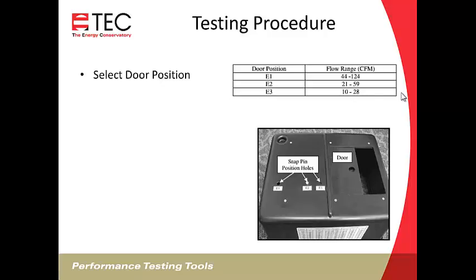If you've got a flow less than 20 CFM, then there's something seriously wrong. I mean, the minimum I've seen on ratings on fans is about 50 CFM. That's pretty typical. And if you're getting flows of less than 20, there's an issue with a stuck damper or a compressed hose, tubing, or the venting, whatever they're using to vent the fan out, has got a kink in it, or a bird nest or something pretty serious.